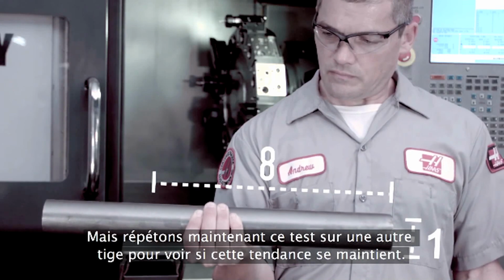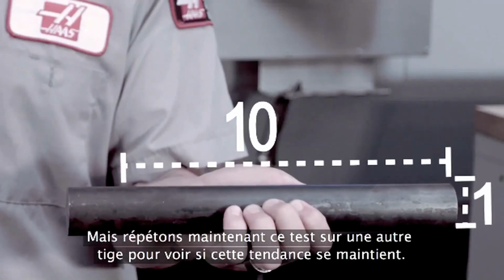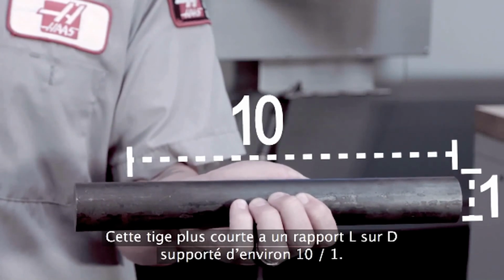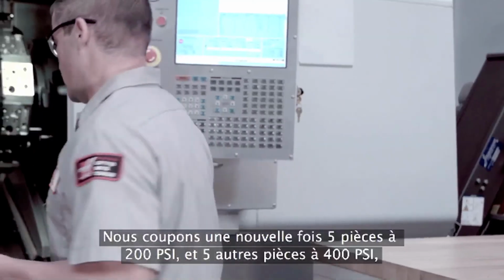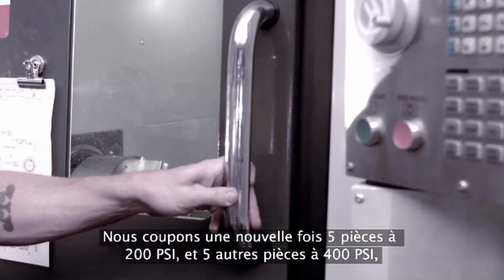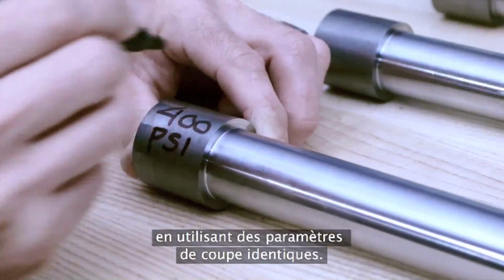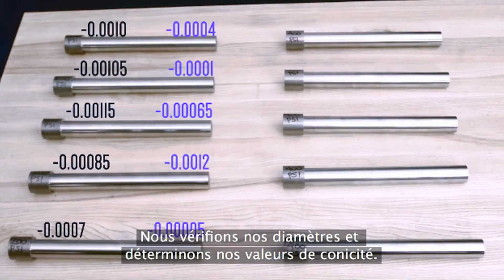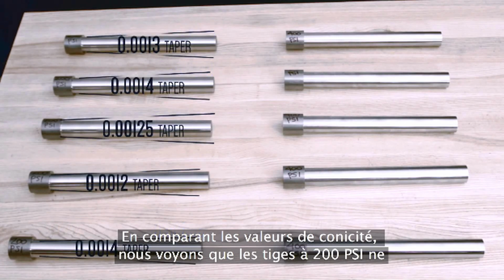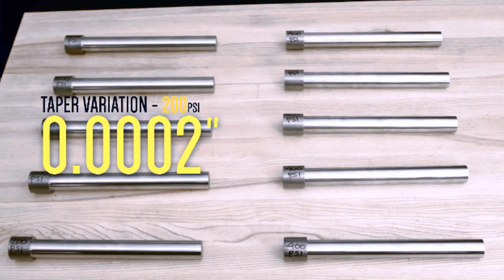But let's repeat this test on a different shaft to see if this trend holds up. This shorter shaft has a supported L to D of about 10:1. Again, we cut 5 pieces at 200 psi and 5 other pieces at 400 psi using identical cutting parameters. We check diameters and find our taper values. Comparing the taper values, we find the 200 psi shafts vary by only 2/10.